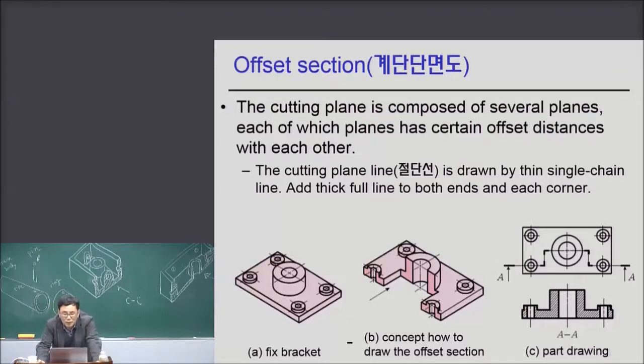Okay, so AA in direction here. The A-A symbol is added under the sectional view. This is a very nice front view, and this is a top view. The front view is drawn by using the sectional view. Even if the projection is from this side, you may see this line here, so maybe you add the thick external line here.